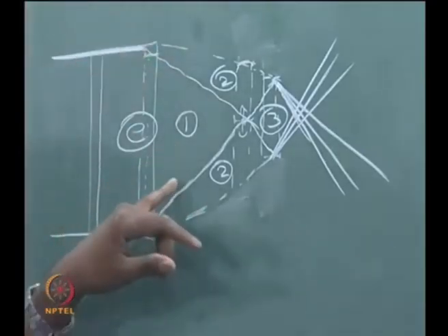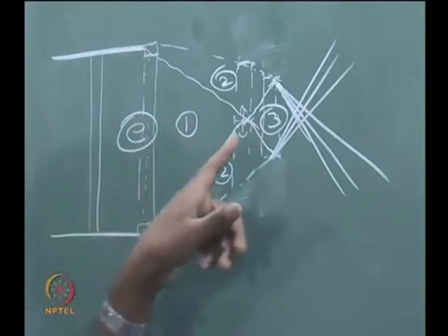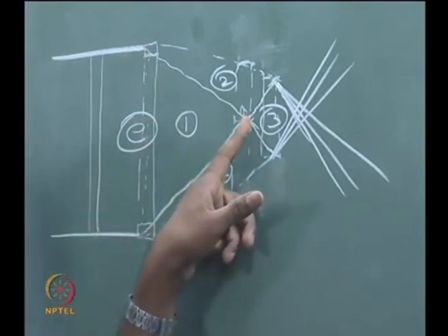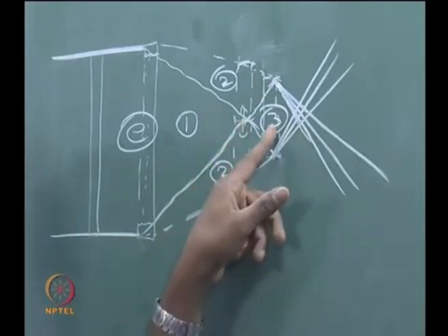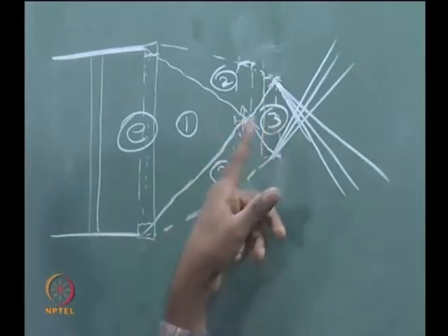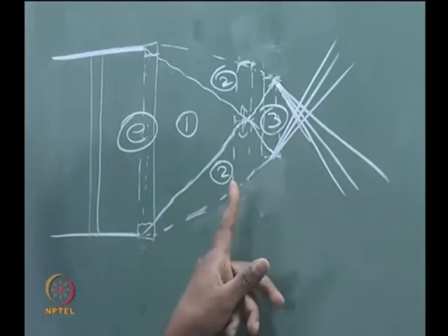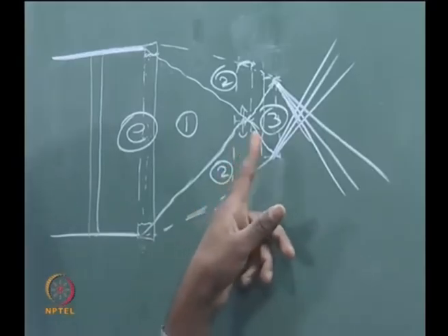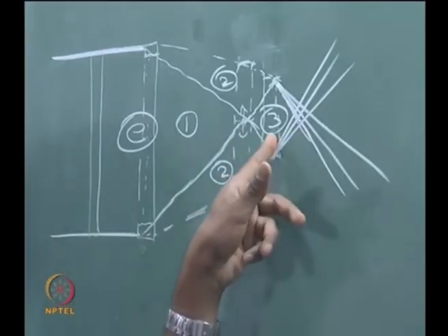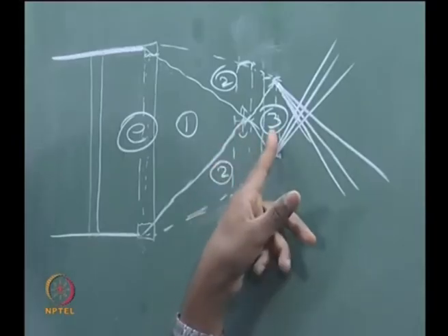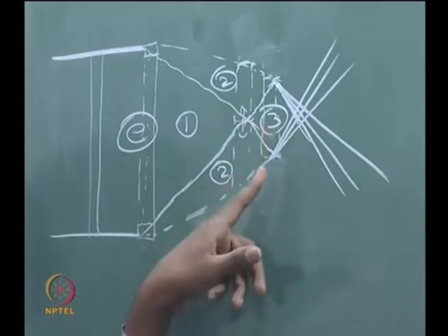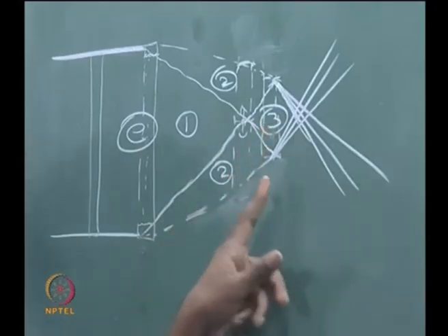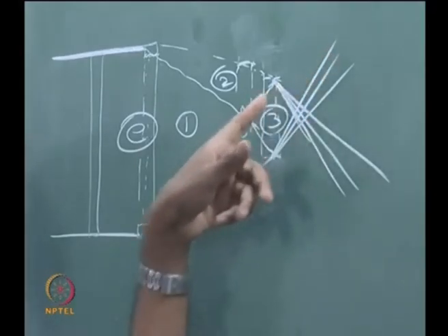Same thing this side, same equivalent shock here, and then because the shock is continuously going past that point, the pressure increased from 2 to 3. 3 is above the back pressure, because atmospheric pressure gas is processed by a shock, so it is going to be higher than that pressure. Now this higher pressure is not liked by the atmosphere, so it is sending out an expansion fan to decrease that pressure.